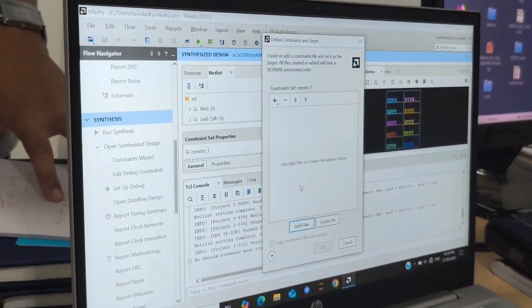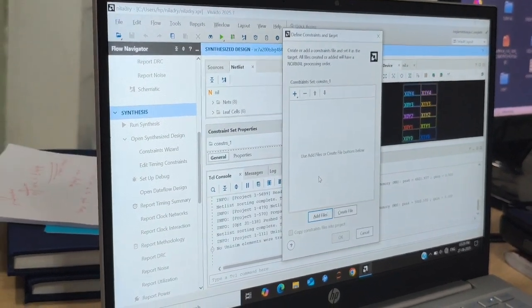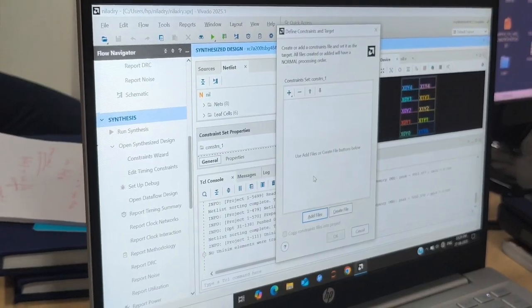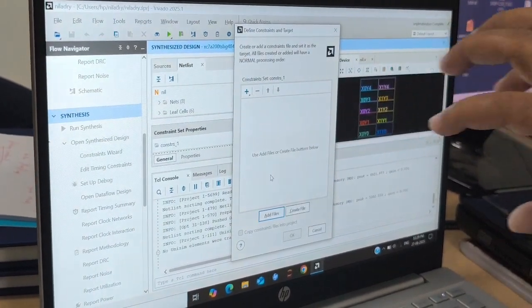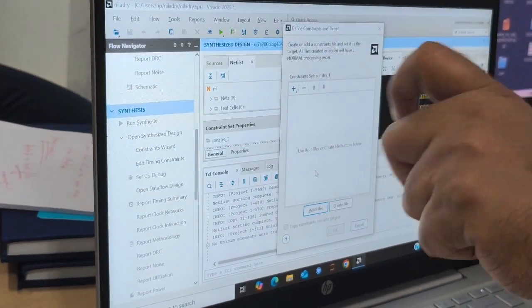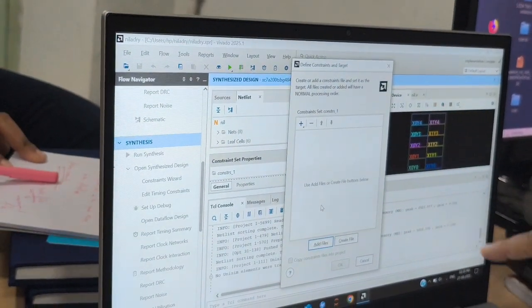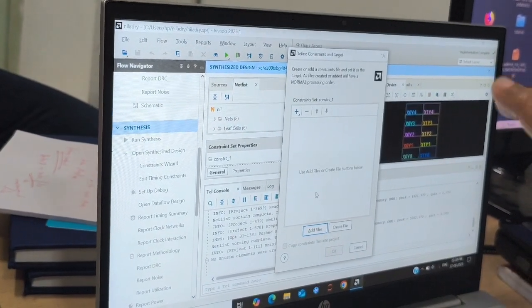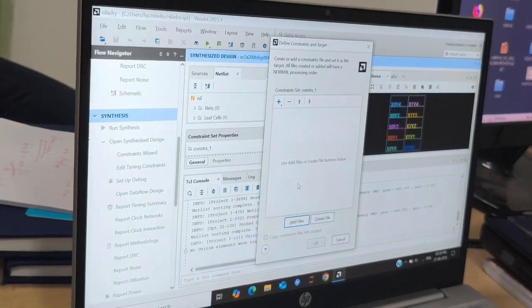If you invert that clock period, that will be the frequency. That means the megahertz frequency it will run at that speed. One by time period is frequency, and that frequency is the operating frequency of the circuit. So with create_clock, you try this using the clock constraint, and then the timing values will come. You have to meet the slack as positive.